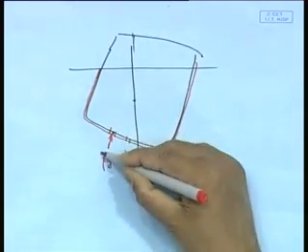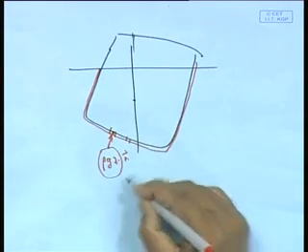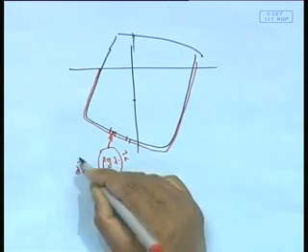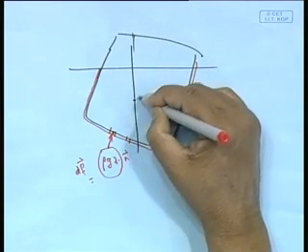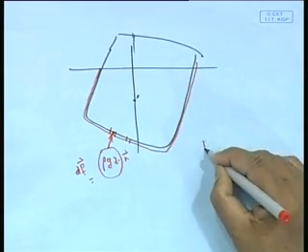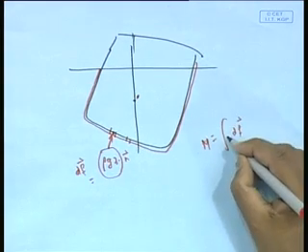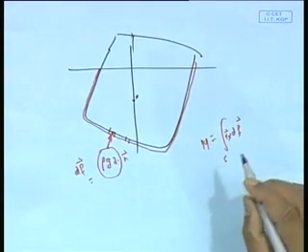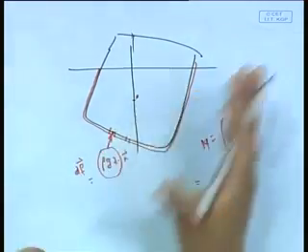This is my hydrostatic pressure. I take this hydrostatic force, call it dF, and find the moment about whatever the CG point, call it R. So the moment equals the integration of R cross dF over the wetted surface S. This is what I found out is the restoring moment.